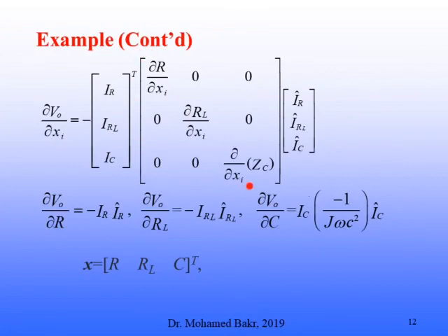These matrices are available analytically. We did not really need to do another simulation to get them. So if your circuit is huge, and it took a huge amount of time to solve, you don't need to do that. Only solve the original responses and the adjoint responses, do this multiplication, and you have all the sensitivities.